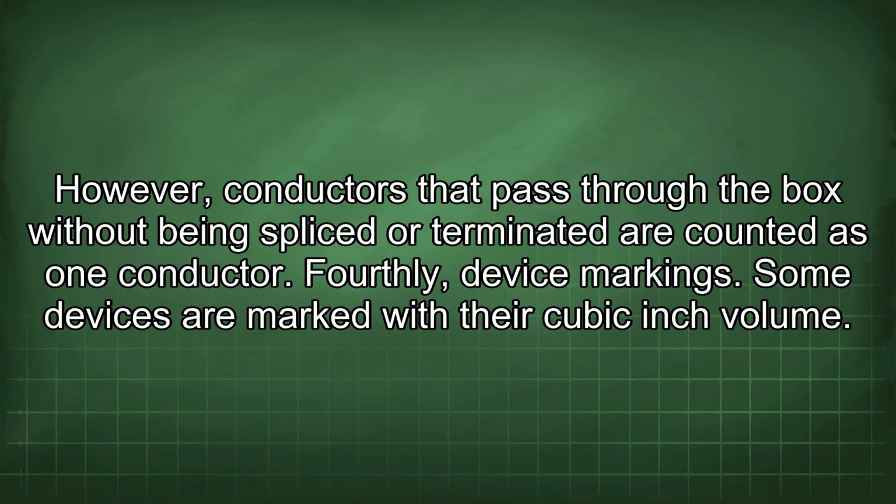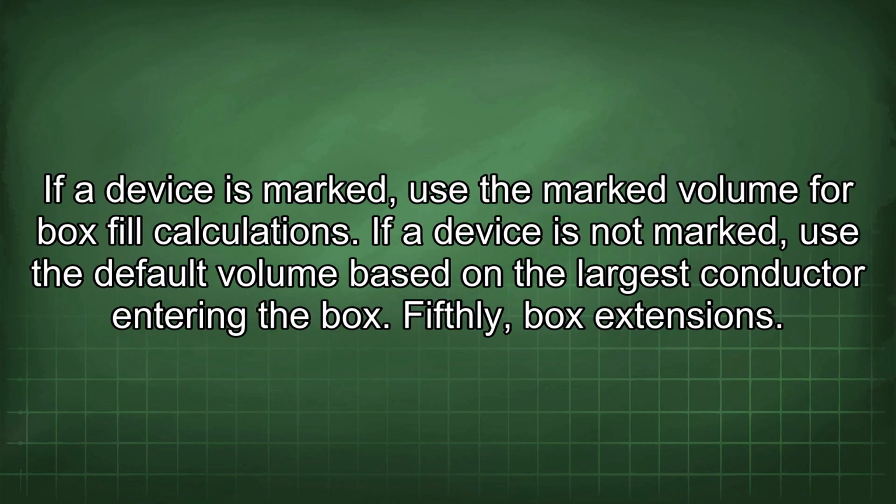Fourthly, device markings. Some devices are marked with their cubic inch volume. If a device is marked, use the marked volume for box fill calculations. If a device is not marked, use the default volume based on the largest conductor entering the box.